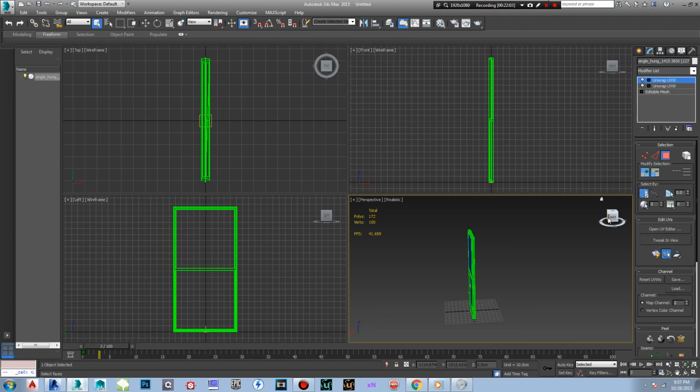That will be the same size as the character that you're using. Let's say you use first person or third person, it will be the same size as that character. So you can use that as a reference point to build your level around it, so it's up to real world scale. That's what they call it when you build in certain scale units in 3ds Max or whatever 3D program you have, and you bring it into Unreal Engine and it matches the default settings. One Unreal unit equals 1 centimeter.